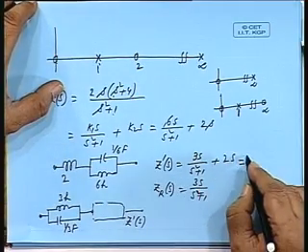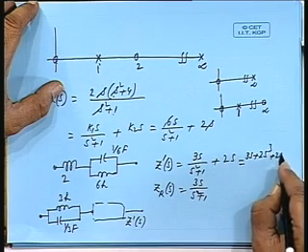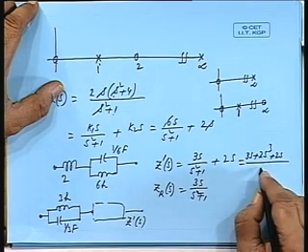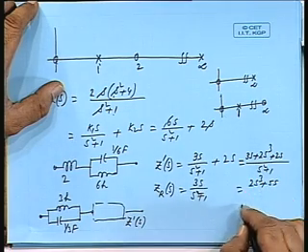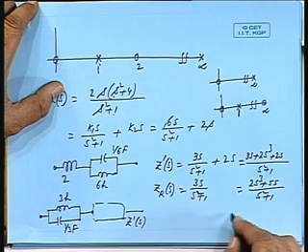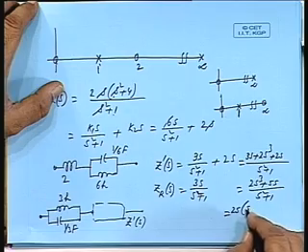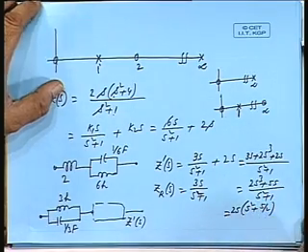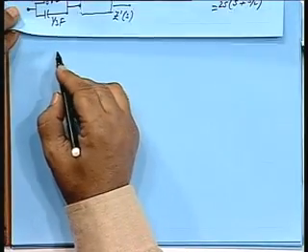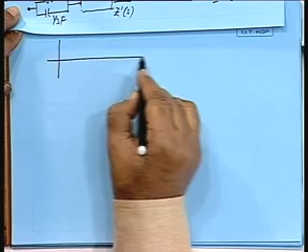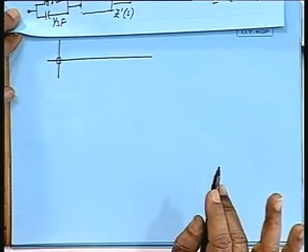So, this will be (3s plus 2s cubed plus 2s) divided by (s squared plus 1), that means 2s cubed plus 5s in the numerator. So, taking 2s common, s squared plus 5 by 2, correct me if I am wrong. Okay. So, the new distribution of poles and zeros: 0 at the origin is remaining intact, all right.